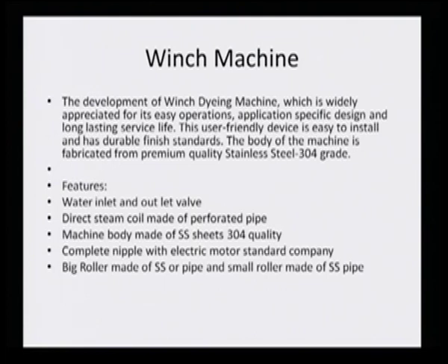So, at a time not much is exposed to the dye bath, but the speed at which this winch machine moves is very fast and very facile, and it does the dyeing in a very uniform manner. The entire body of the winch machine is made out of stainless steel. There are inlet and outlet valves, and there is a direct steam coil which has perforated pipe. So, the steam is being controlled through these perforated pipes.